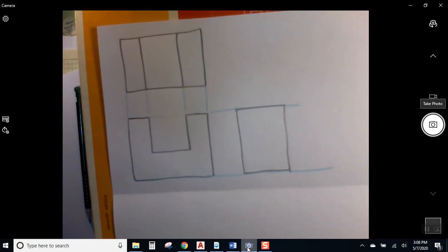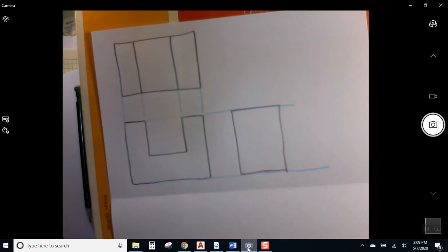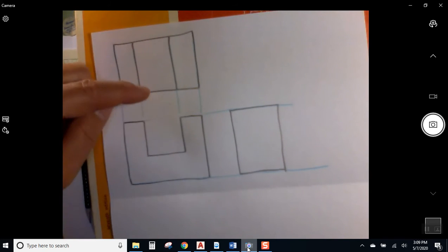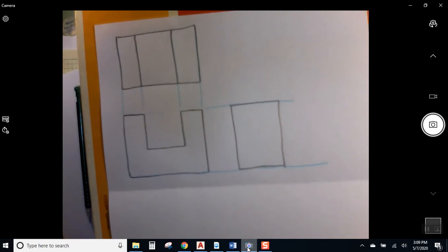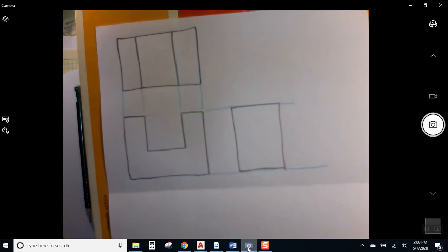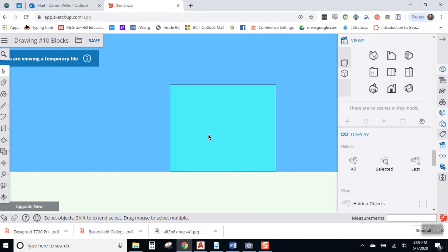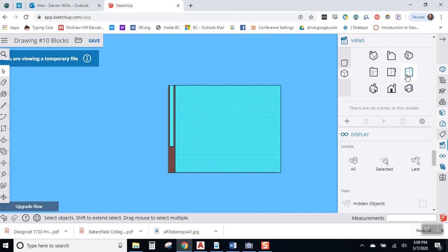There is a problem with this drawing though. I can tell from the front view that there's this notch cut through the block. And I can even see in the top view, this is a little canyon that that notch makes, goes from front to back. What I'm not seeing though is any evidence that there's any notch at all in the side view. And of course that's because you can't see through objects, right? That's an opaque object, and yeah, that canyon, that little cutout is back there, but we can't see it because, again, we don't see through objects.